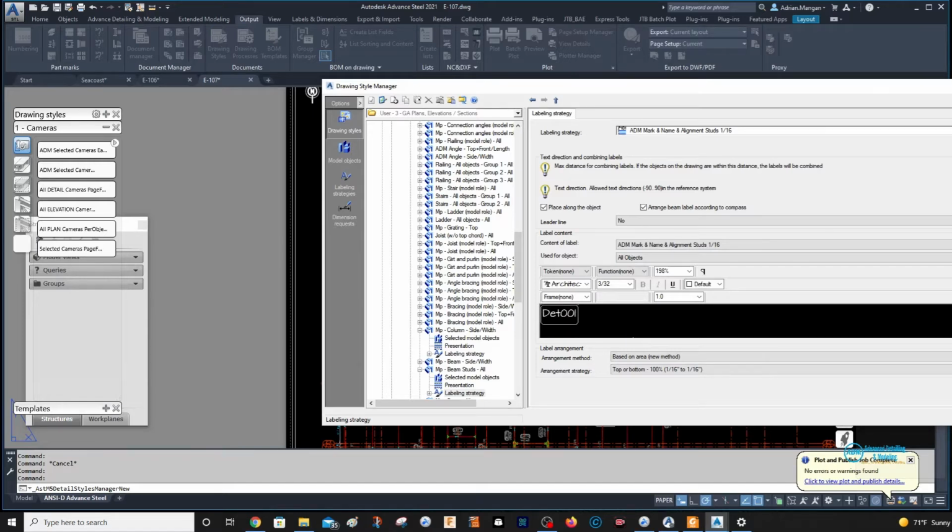Alright, so now we have our text. Just keep in mind, you need to try and grab everything, or it probably won't work. Sometimes it's better to turn off this box and then turn it on again. So let me do it that way, grab everything, and then change this to 1/16. Then click in here on the black area, there you go, and then come back in here and put that back on. Sometimes it looks like there's a line up here, but there's not.